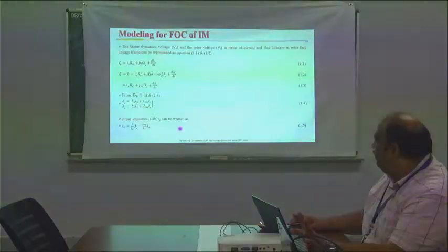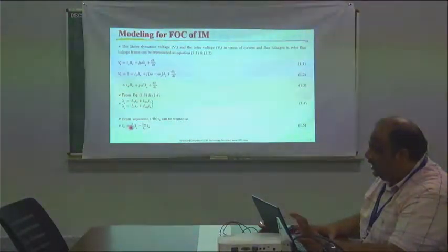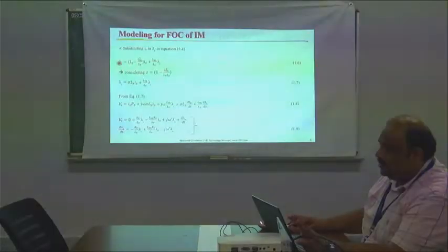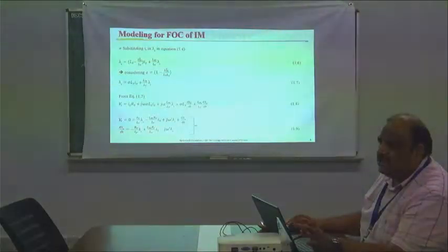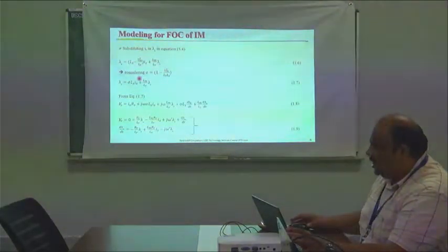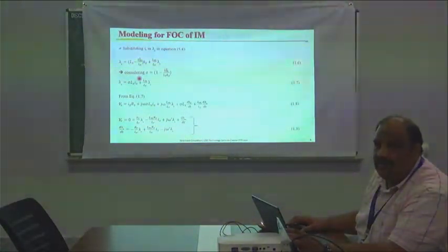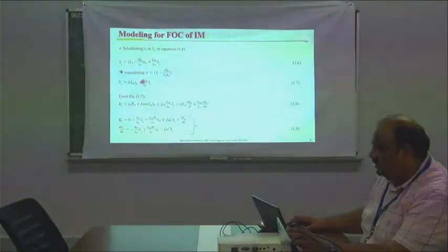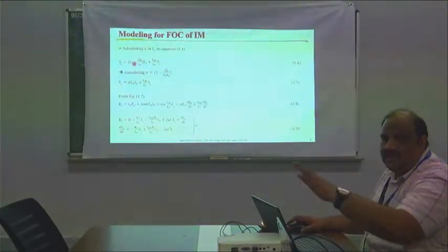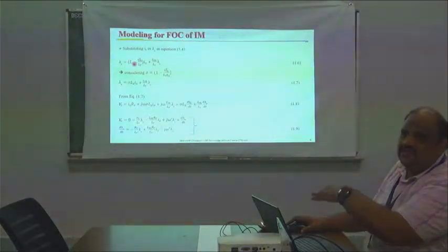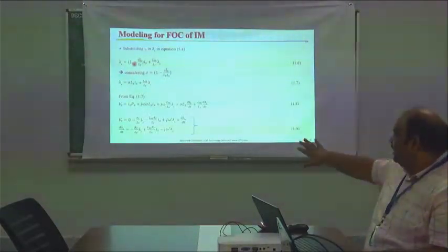In a similar way, when you rewrite this equation, you get the current IR in this form. Finally, by deriving, you get single components. That means I am just making it more simplified to understand how the FOC is running. It is not a big equation. If you link it from the previous, it comes as a flow, but if you see it as an instant, it looks clumsy.